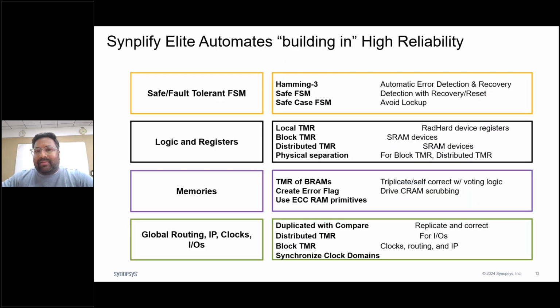Now let's look at how the high reliability feature is available in Synplify. To protect your FSMs, it supports safe FSM as well as safe case FSM, and at the same time it supports three error detection and recovery techniques for your FPGA. So you don't have to add extra logic for this; once you enable it, the tool will automatically put that reliability in your design.